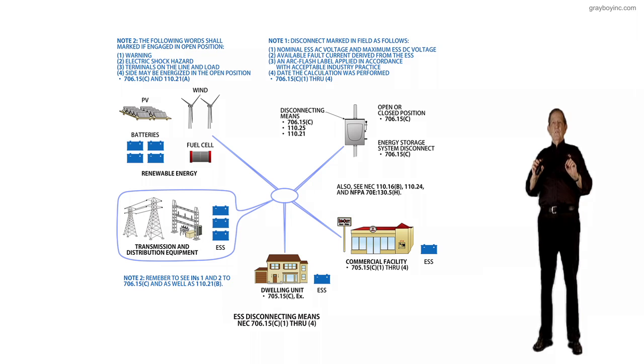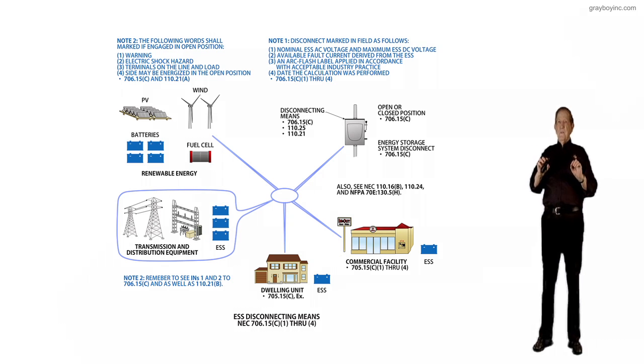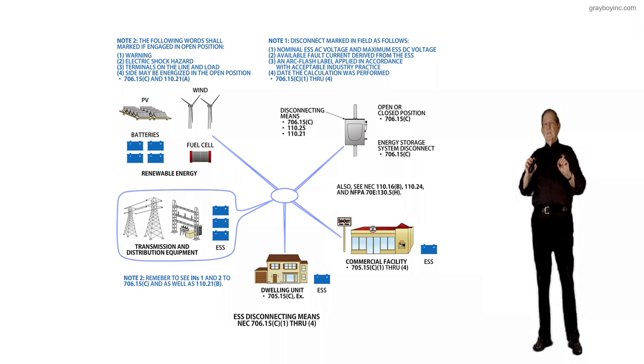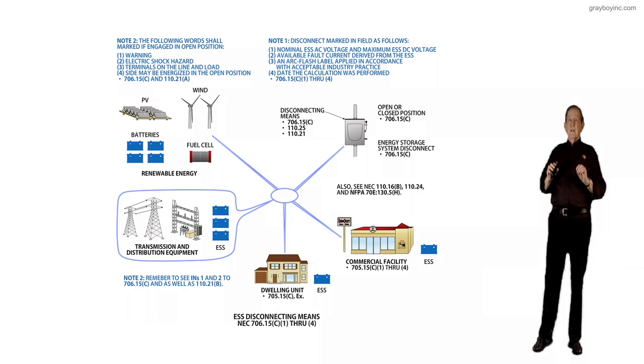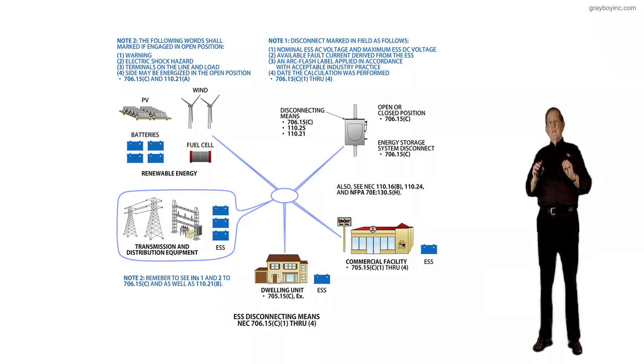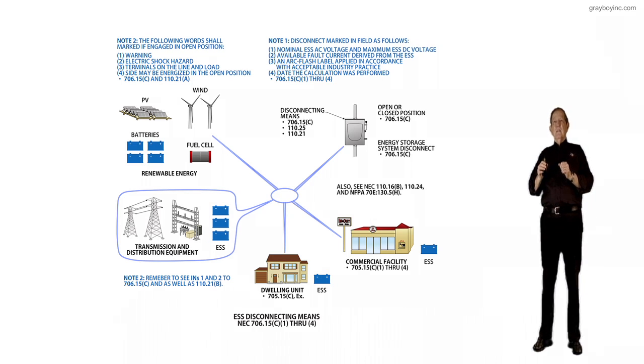So the NEC is trying to let the designer, installer, or inspector, as well as the maintainer, know that there are labels that have to be put on this equipment identifying your disconnect and also indicating the on or off for safety. But notice the NEC now is accepting proposals to design and install the disconnecting means so that 70B and 70E can be enforced and have the working space to do so.